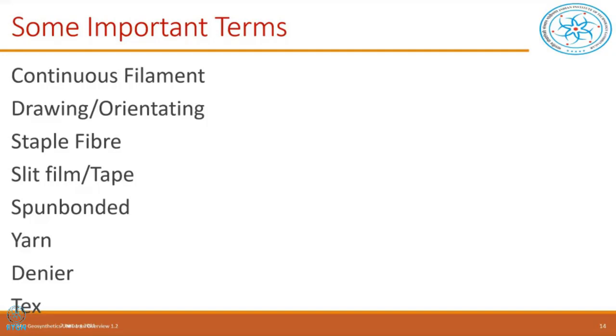Okay, and the staple fiber now is very typically similar to cotton now. Cotton has also got fibers, small pieces, but they are varying in diameter, varying in length, and varying, you can say, in shapes also. Okay, so this is somewhat similar to that now. So we'll use it for certain purposes. We'll see that also later. So all along we're trying to say that the extrusion is happening actually in a circular hole. Very rarely it can be a triangular hole also. So the filament is going to be triangular in shape, but it's not always common.